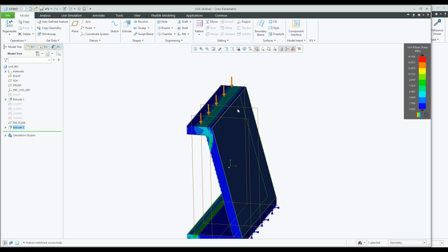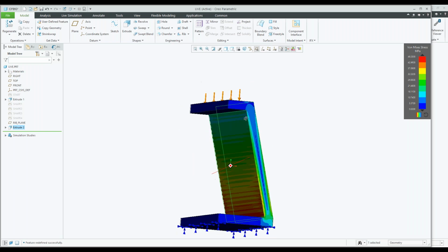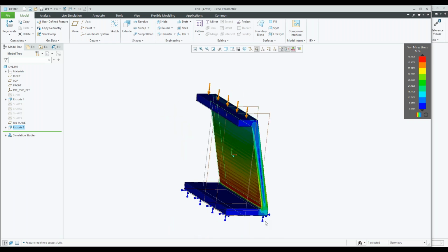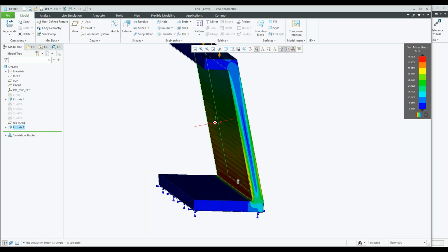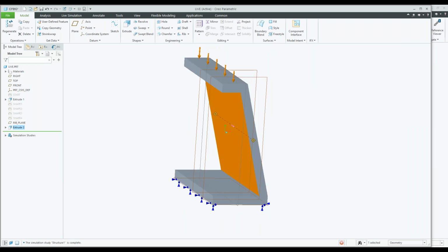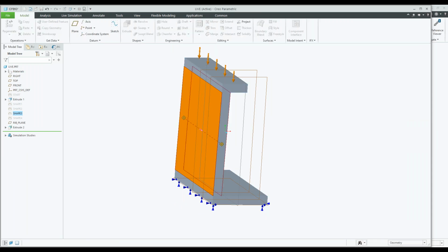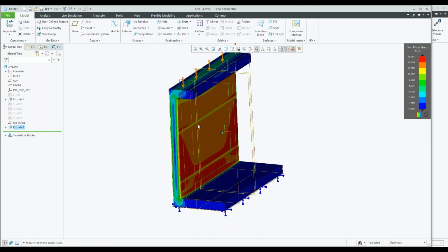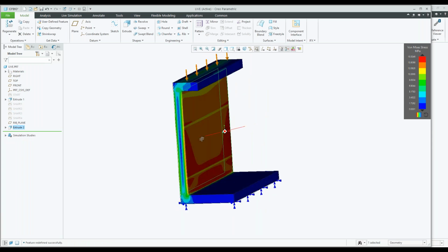Okay, so that might work for us. Our stress here is a lot less than the previous shape. I'm not too happy about this, but maybe we can add a chamfer in here to stiffen that section a little bit. That might be an option. Let's edit definition on that. Let's go to shape 3 that I've created. Let's do analysis on that. Okay. So we're sitting a little bit higher here. We'll need to change much more on this one.